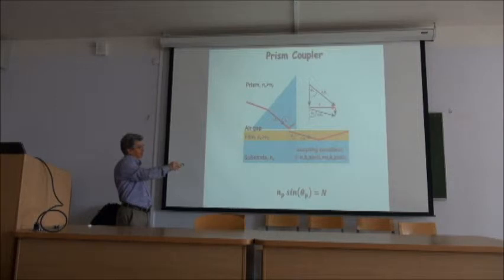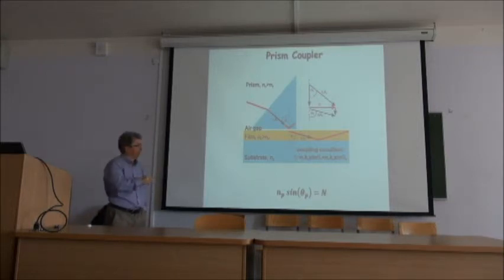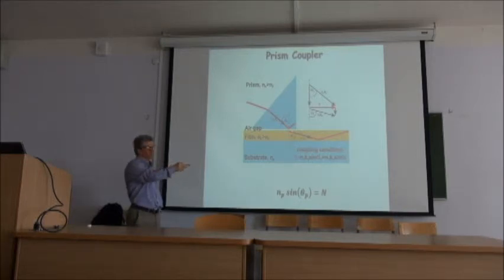But at the same time, light you put in also gets out. And the rate at which it goes out depends on this gap here. If this gap is very small, or if the refractive index here is very high, then it decays very fast, and it's very hard. You need to put the beam extremely at the edge, and this edge must be perfect, and it's very tough to get prism coupled light into a waveguide.